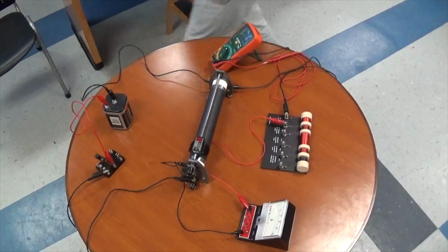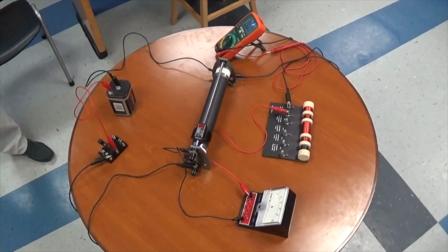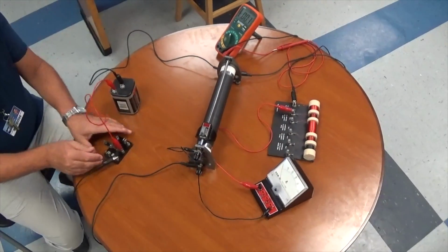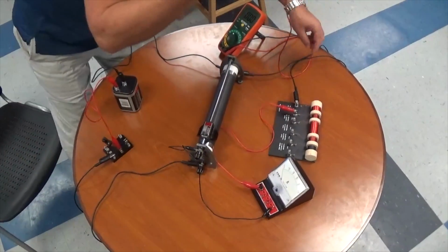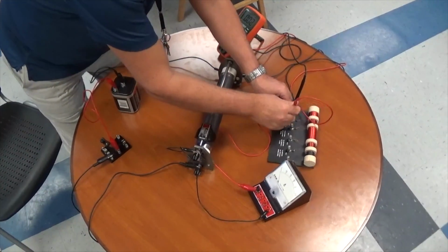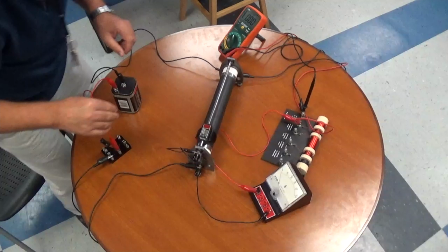Then another alligator clip is used from the positive end of the resistor spool to the single capped end of the rheostat. At this point, there should be two wires on this cap. The last step is to take the positive end of the potentiometer to the positive end of the resistor spool, and the negative end of the potentiometer to the negative end of the resistor spool. And now you have completed your circuit.